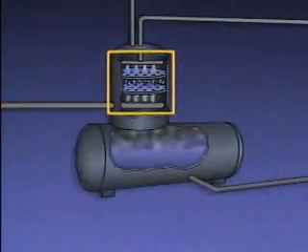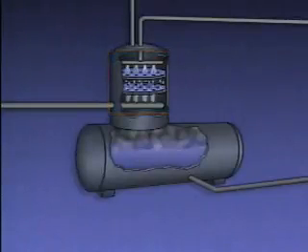The trays help lengthen the period of contact between the water droplets and the steam. The deaeration process strips away most of the dissolved oxygen and other gases in the water. The released gases collect at the top of the deaerator and are vented off through a vent line. The deaerated water falls into a storage tank.